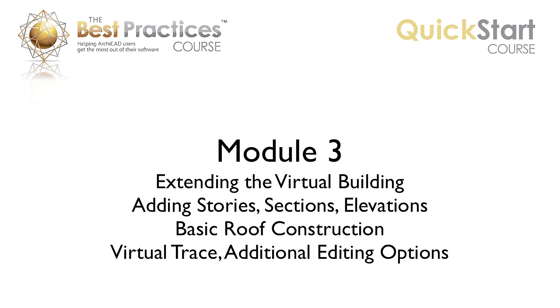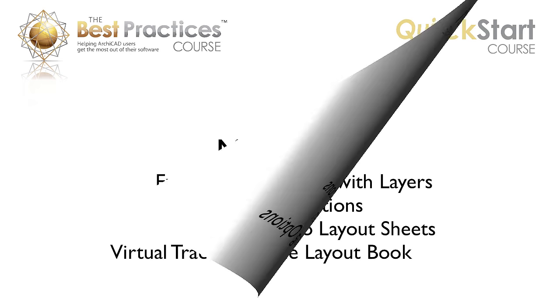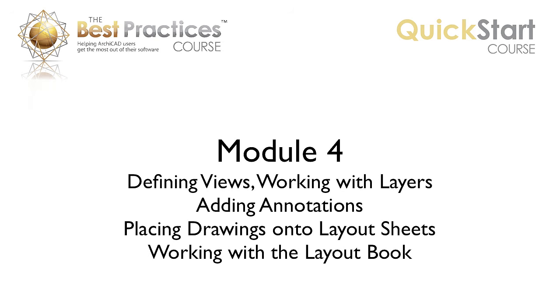We'll start to look at how you construct roofs, and we'll examine how Virtual Trace, a powerful feature introduced in ArchiCAD 11, allows you to ghost or overlay one drawing on top of another or beside another to be able to compare and coordinate information. And we'll look at some additional editing options which allow you to move things around and reshape them in a variety of ways.